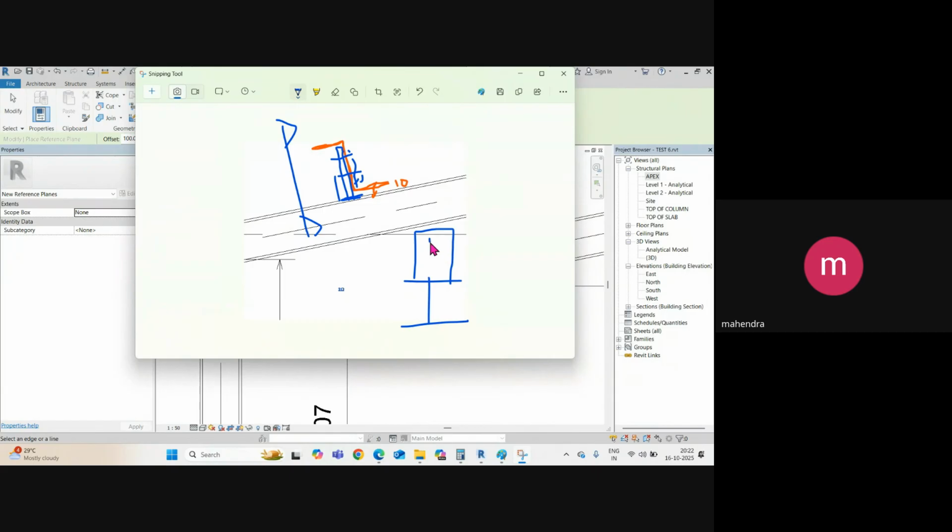Okay, and one bolt here and one bolt here, and then your purlins is running behind. Okay, like that. Then here also dotted line, and then you can add your purlins, and this is again behind the plate, should be shown in dotted lines, right? And then you can add the two plates, and this plate is welded on the top of the rafter in fabrication, right here. So this is how the connection looks.